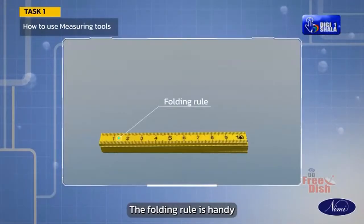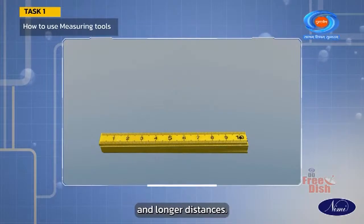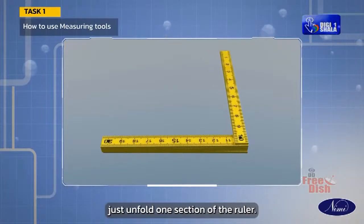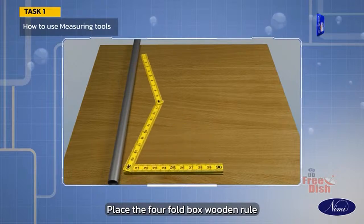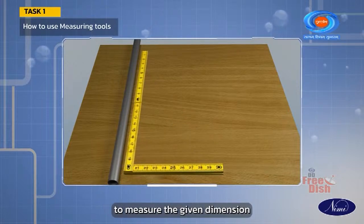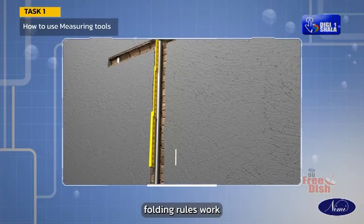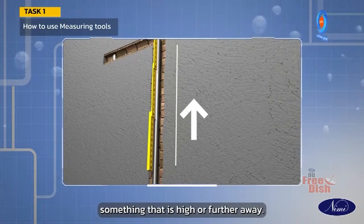The folding rule is handy for measuring both shorter and longer distances. If you need to measure something small, just unfold one section of the ruler. Place the 4-fold box wooden rule to measure the given dimension on the workpiece. Mark the measured portion. Folding rules work well when you need to measure something that is high or further away.